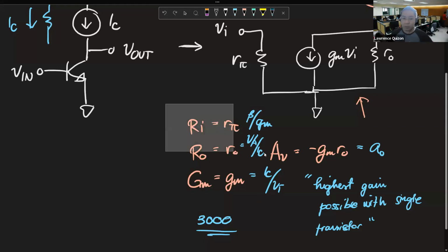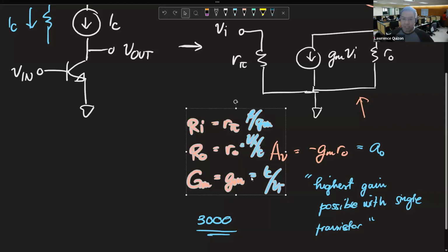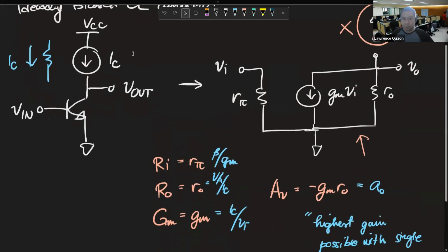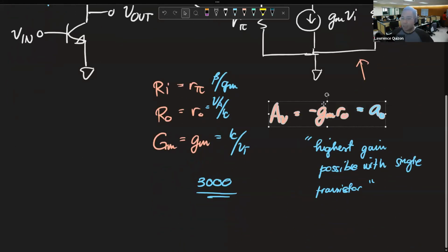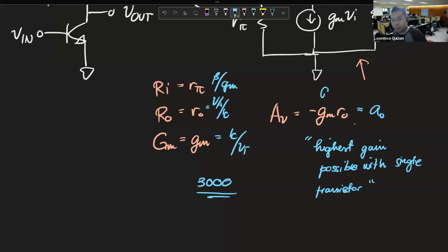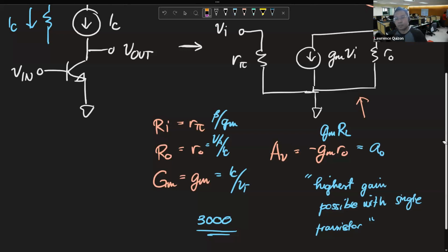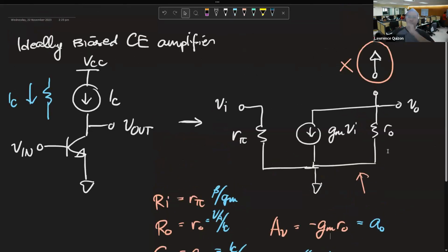No? So for comparison's sake, you would, yes, desire to make this the same IC as the one that we had earlier. No? So assuming this is the same IC as the one we had earlier, then this gain will definitely be much higher than the other one, no? By the factor of the difference of gm, of R_L and r_out, no? All right?